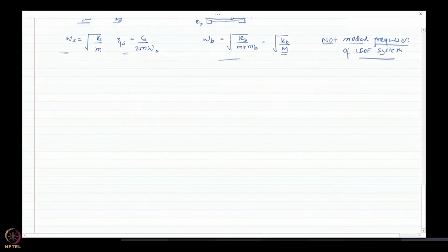So in general, can I say the stiffness of the isolation layer KB would be much smaller than Ks, the superstructure stiffness? These are the assumptions for a base isolated structure. Now, do we have this or not? We say that the base isolation layer is much more flexible compared to the superstructure, right? In a base isolated structure. So this assumption is okay. For a base isolated structure, the base isolator stiffness is much smaller than the superstructure stiffness.